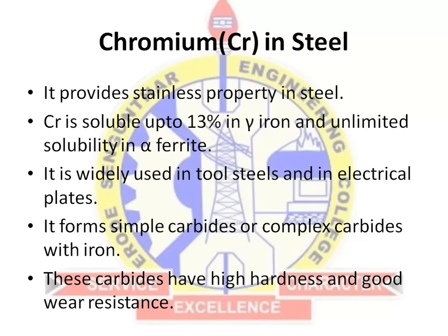It forms simple carbides and complex carbides, both formed in the process with iron. These carbides have high hardness and good wear resistance. So actually, chromium plays a vital role in wear resistance.